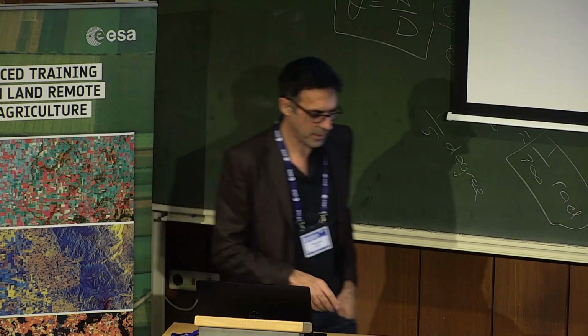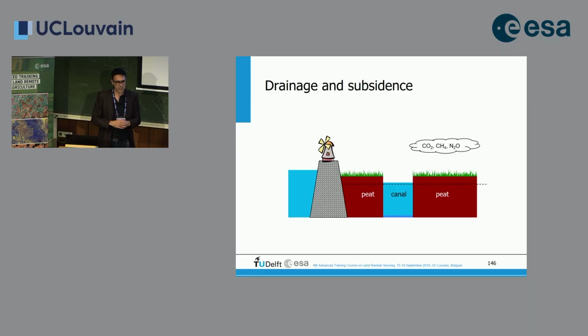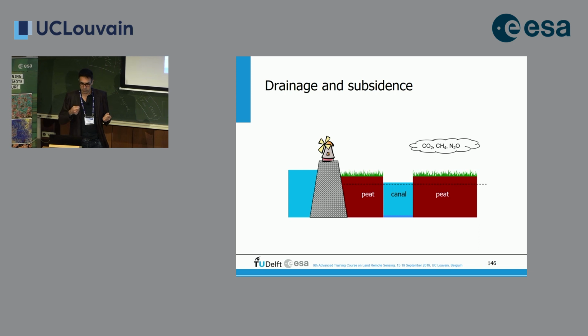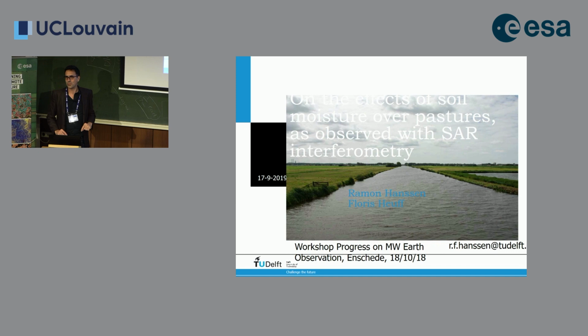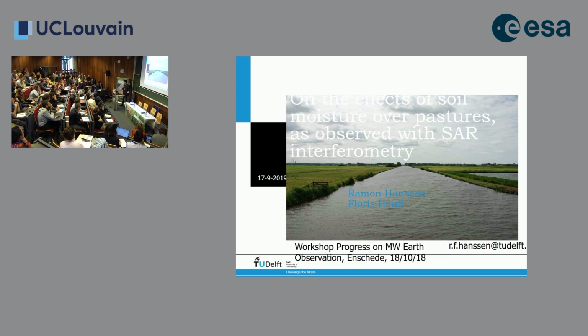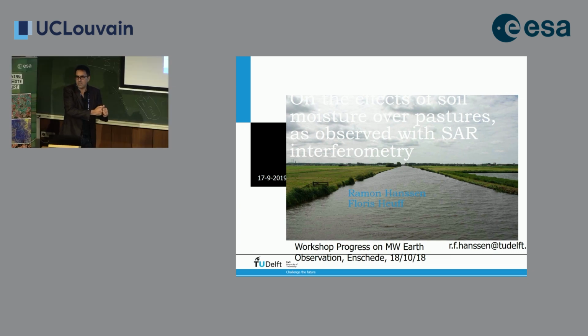The problem in geodesy of measuring heights is usually dealt with by leveling, right? So you hammer a bolt in a wall, you put a leveling rod on it, and a surveyor measures the height of that bolt, and comes back next year and repeats it, and if the bolt is lower, you will be able to measure it. And the problem is that in grassy fields, like we have over here in the picture, there's no way to put a bolt somewhere because the bolt would drown by itself. If you don't have a bolt, you can put your leveling rod there. But if you come back next year, if a cow has just put its feet there, the height would already be changed. So it's very, very difficult to measure this.